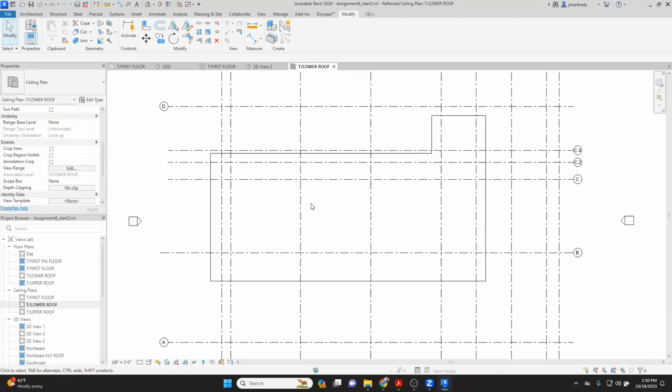So again, Revit cuts through the view range, looks down, and the floor becomes a mirror. But when you look down, you can't see through things. Like the walls don't become invisible. So wherever you cut through the model, it cuts through at a certain height, looks down on top of the floor, and reflects whatever's above you on top of the floor. That's why it's called a reflected ceiling plan. So what happened here? Why is it not cutting through my windows?